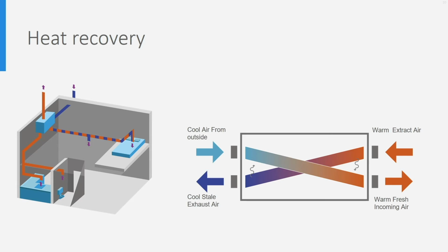The warm exhaust duct is placed very close to the cold air supply duct, by which heat goes from the warm duct to the cold duct, preheating this way the incoming air. This will reduce the ventilation losses significantly. And the advantage of this system is that the airflows are really not mixed, which would pollute the incoming air.